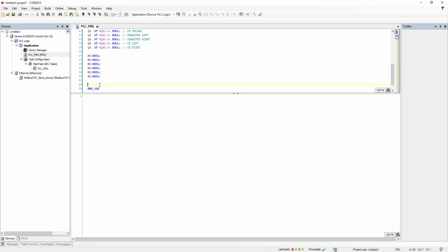then do the same with the T timers, T0, N. So this one, I don't have a problem. You can say timer underscore 0. Then it's a TON. It's an on delay timer.